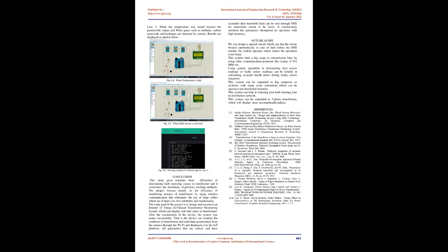This work includes the process of monitoring the transformer oil's temperature range and the gases present in the oil as well as the transformer tank. The sensed values are given to the Arduino. The values given by the sensors are measured and compared with the nominal value predefined in the program in the comparators. If the measured value varies, the system will send an alert to the concerned person with the help of a Wi-Fi module, and as a physical indication the buzzer gives a beep sound and an LED bulb glows. The programmed output is displayed through a local LCD screen.